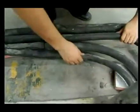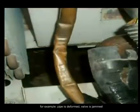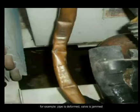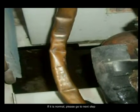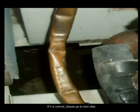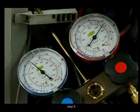Step 4. Check if the liquid side pipes are jammed. For example, the pipe is deformed, a valve is jammed, or the shutoff valve is not open, and so on. Check it one by one. If it is normal, please go to the next step. Step 5.